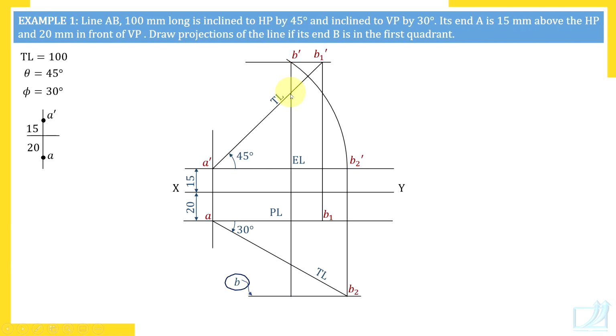Now when you draw this vertical line, it intersects many lines. But not all these points of intersection are significant. We know where exactly point B is on this line. So extend that line, that projector, up to this horizontal line, and here you will get B. Check here, B and B2 are on a horizontal line.